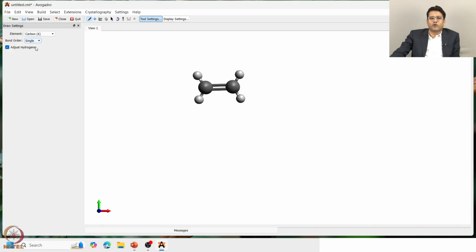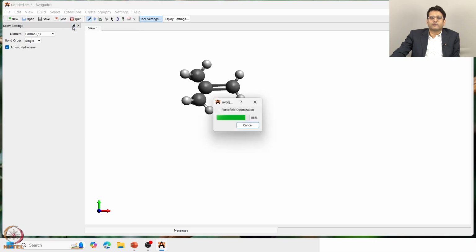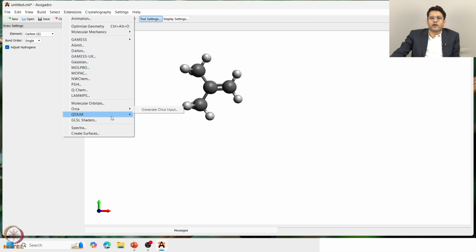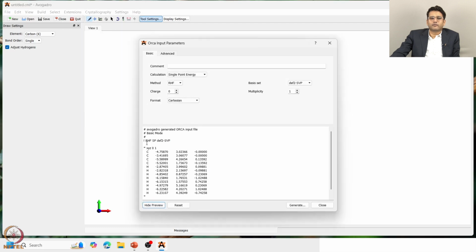Now, I make the bond order to be 1 and replace this one by CH3. And I can make an ORCA input file. RI BP86. I want both opt and freq.